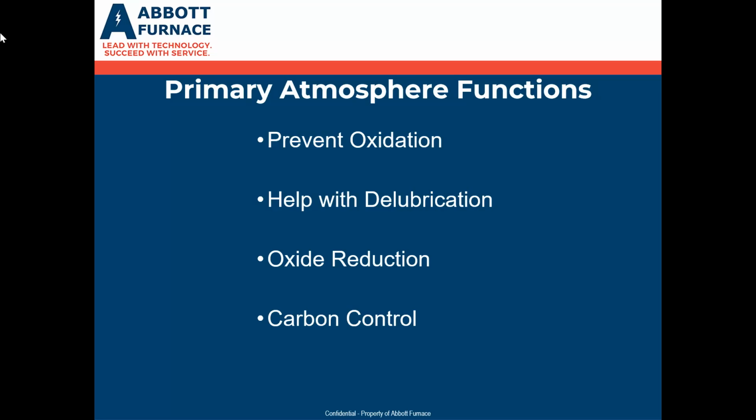As we increase the temperature up to our bonding, our sintering temperature, those particles are all going to have a coating of oxide on them, usually from the water atomization of the powder. So that hydrogen in the atmosphere, the reducing gas, is going to reduce those oxides off the particles in the parts, so that we can get the bonding when we get up to temperature.